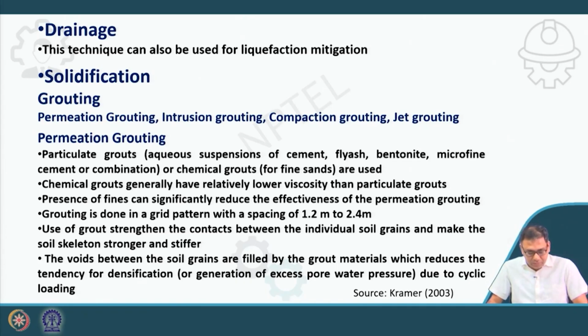Grouting is done in a grid pattern with a spacing of 1.2 meter to 2.4 meter. The use of grouts strengthens the contacts between the individual particles or soil grains and makes the soil skeleton stronger and stiffer. So, as I have discussed in my previous lecture, it makes it a solid material.